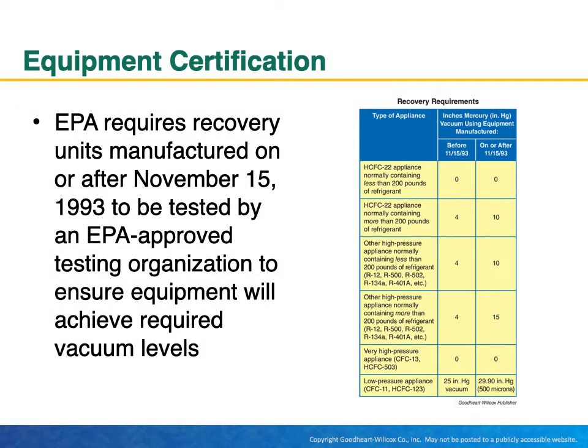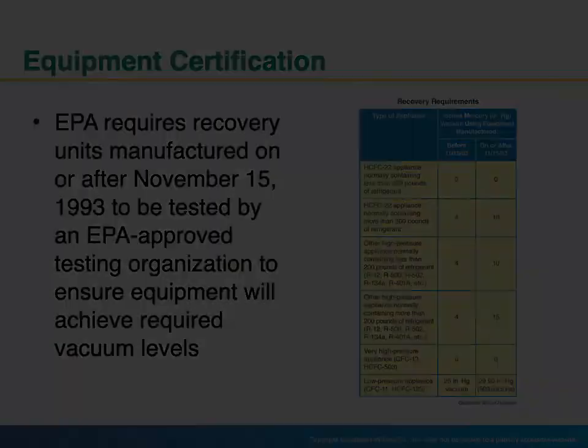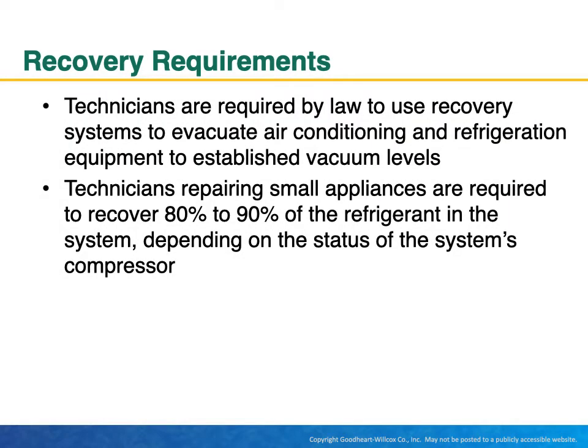Equipment certification. EPA requires recovery units manufactured on or after November 15, 1993 to be tested by the EPA-approved testing organization to ensure equipment will achieve required vacuum levels. Recovery requirements.